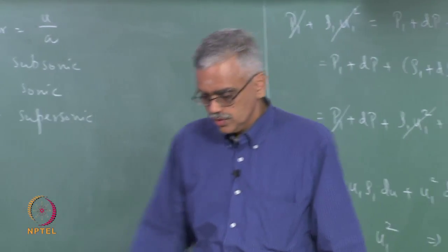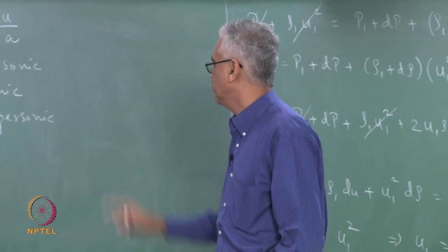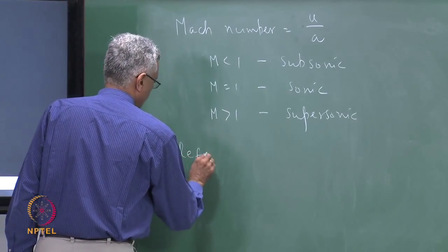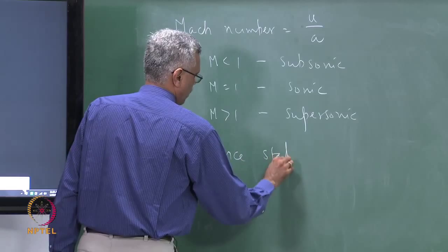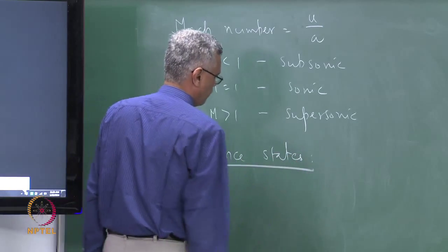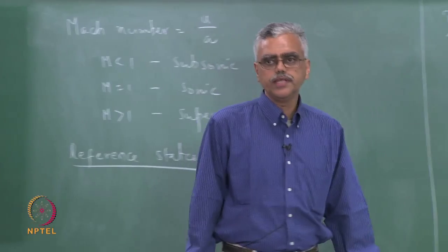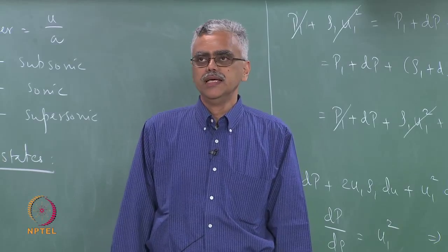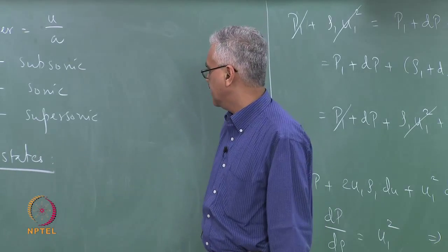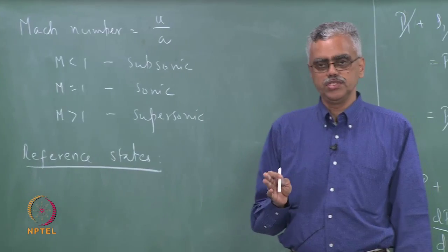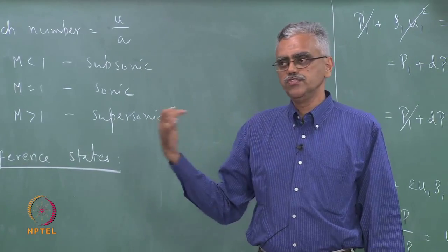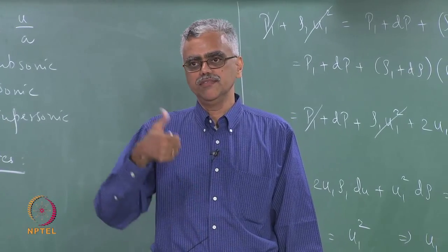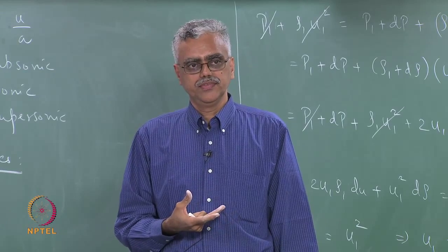Okay. So, those are some important ideas about the Mach number, and the next fundamental idea that we are going to look at is the so called reference states. Reference states are very useful in fluid mechanics in general and in compressible flow in particular. Okay. It is possible in gas dynamics that we can simplify the governing equations. The governing equations, if you remember, for one dimensional flow involve three unknowns, right, depending upon your equation of state, let us say velocity, pressure and temperature, right.